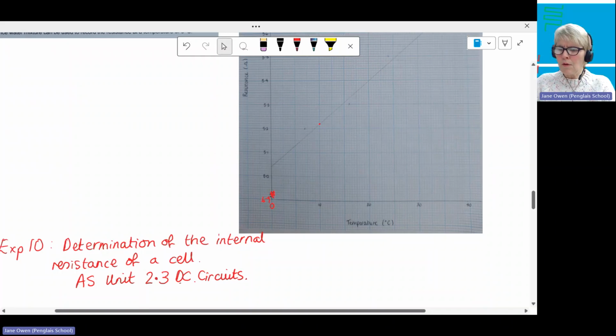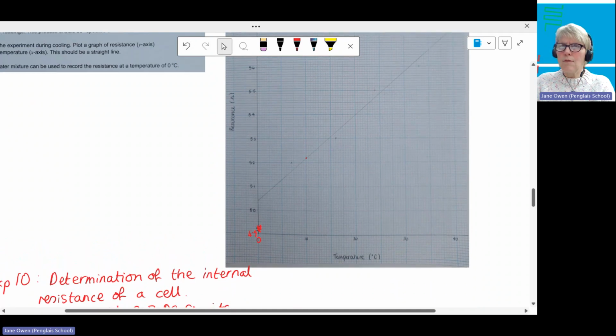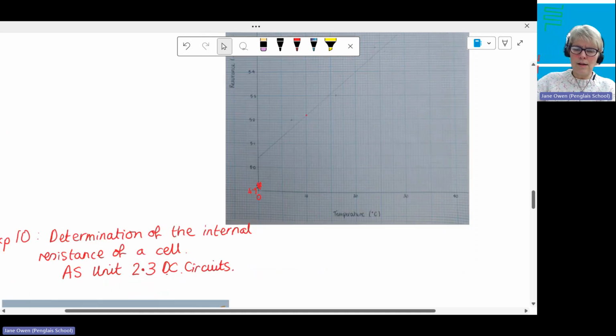Okay, I'll leave that with you, because resistance is all to do with the vibrations of the atoms and the resistance to those electrons flowing through. So if those atoms take up more volume because they're vibrating more, because they're at a higher temperature, then there's clearly a bigger volume for the electrons to bump in and collide with those atoms, with the electrons of those atoms, and provide a greater resistance to the flow of the free electrons. So as temperature increases, you expect resistance to increase, and in fact, it does it linearly.